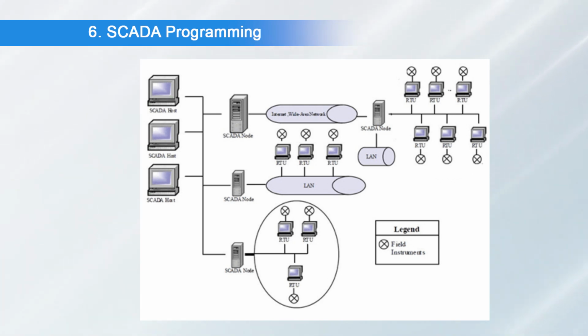The above figure depicts an integrated SCADA architecture which supports TCP/IP, UDP and other IP based communication protocols, as well as industrial protocols like Modbus TCP, or Modbus over TCP or Modbus over UDP. This all works over cellular, private radio or satellite networks.